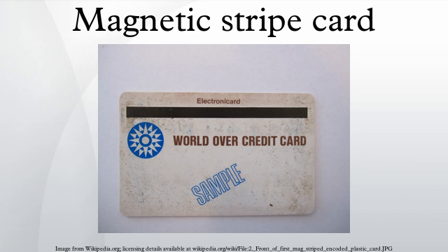Financial cards. There are up to 3 tracks on magnetic cards known as tracks 1, 2, and 3. Track 3 is virtually unused by the major worldwide networks, and often isn't even physically present on the card by virtue of a narrower magnetic stripe. Point-of-sale card readers almost always read track 1, or track 2, and sometimes both, in case one track is unreadable. The minimum cardholder account information needed to complete a transaction is present on both tracks.